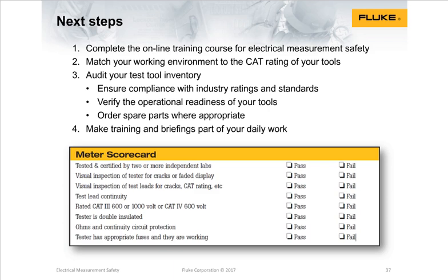And when you look at your meters, take a look at the accessories, take a look at the meters, look at the case for cracks, or any seals or oil leaking from them, or a defective display. Make sure you look at all of this before using it. And that brings me to the end of my part of the presentation.